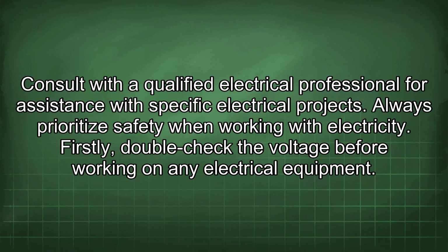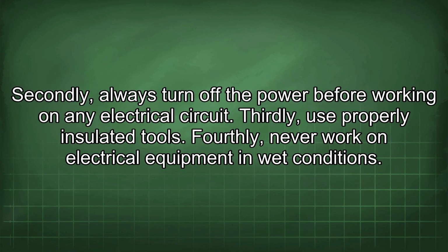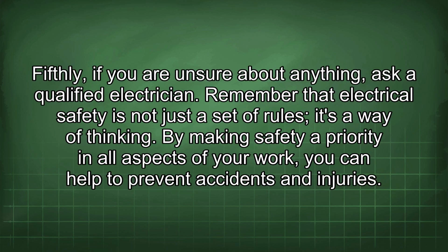Firstly, double-check the voltage before working on any electrical equipment. Secondly, always turn off the power before working on any electrical circuit. Thirdly, use properly insulated tools. Fourthly, never work on electrical equipment in wet conditions. Fifthly, if you are unsure about anything, ask a qualified electrician.